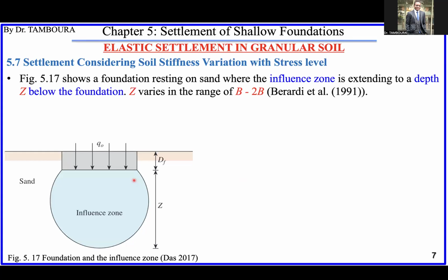If you go back, you will see that when you load, depending on the shape of the load on the surface, there is a distribution of the stress in the ground according to the depth. So we suppose that here is your footing. When you load the footing, you will have this kind of pressure bulb inside.